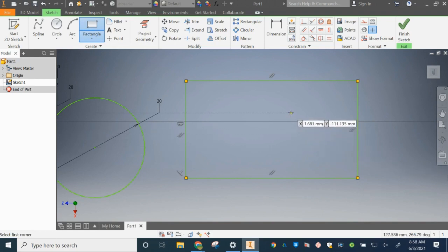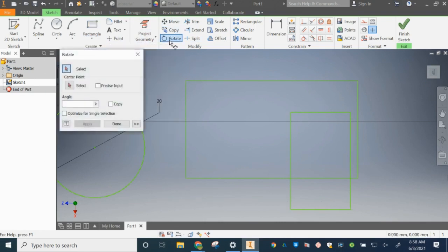Okay, so now we're going to do some other things by actually changing the lines on our drawings. Well, actually, first we're going to show you the rotate tool. So we're going to choose the rotate tool. Again, the first thing that you do is select. Now there are multiple lines to select, so at this point it's easier just to go from left to right. See that red box?